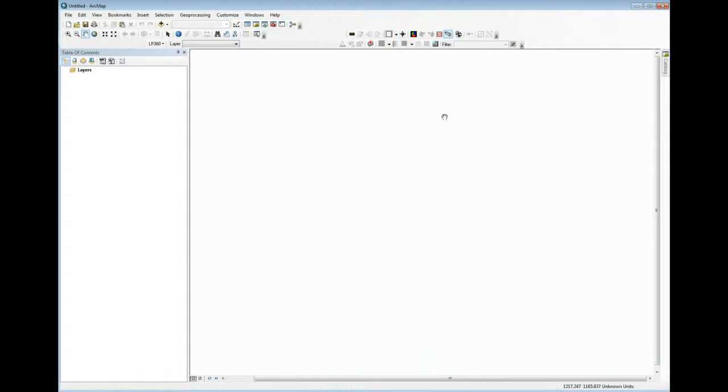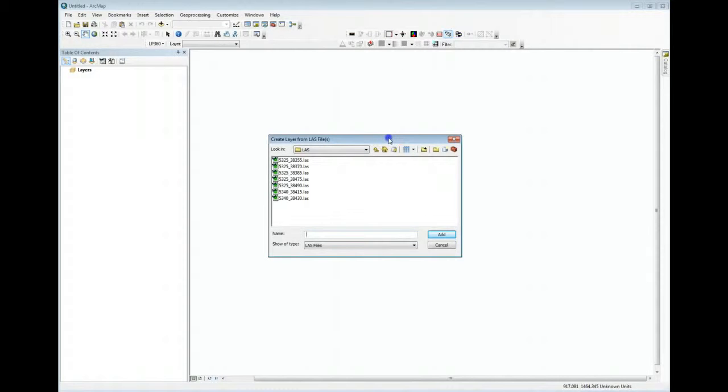The first thing you want to do is load some LiDAR data, or elevation and point cloud format. We can load two formats of data, LAS and ASCII. If you load ASCII, we'll convert it internally to LAS. Now you don't want to use the data load button within ArcGIS. You'll want to use the data load button within LP360, and this is a little stack looking icon with a red plus on it. Click on that, you'll bring up a file browse menu.